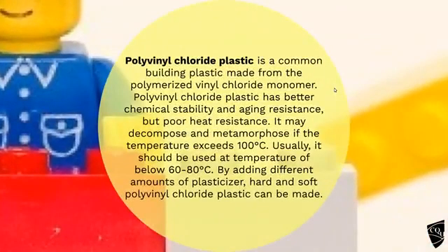So polyvinyl chloride plastic, that's quite a popular one, very common in construction. It doesn't age very quickly, but it doesn't like heat. So it's no good putting it somewhere that's going to get hot.